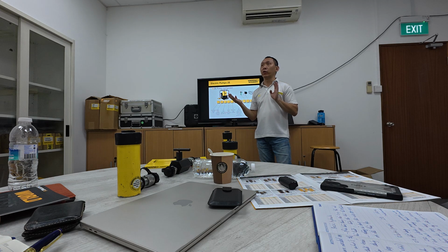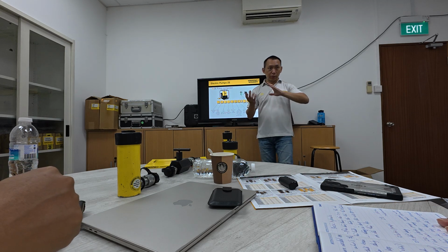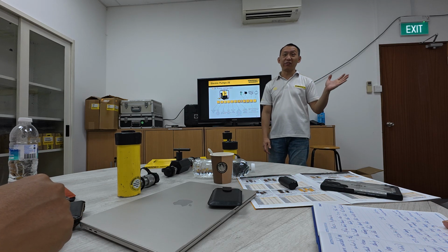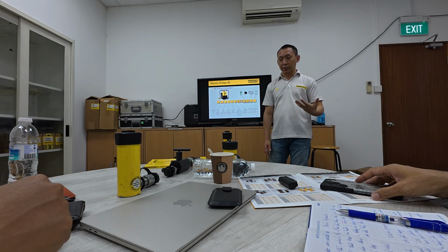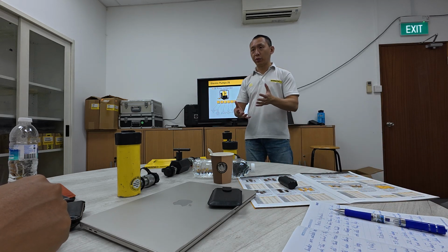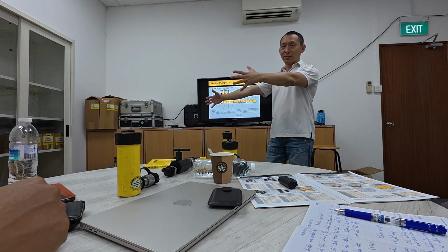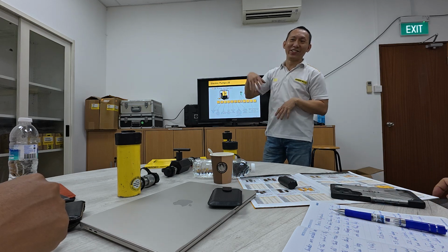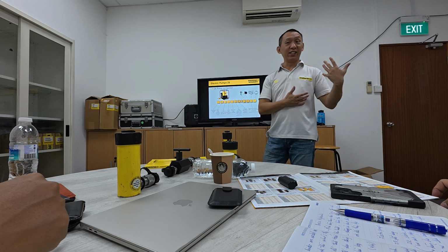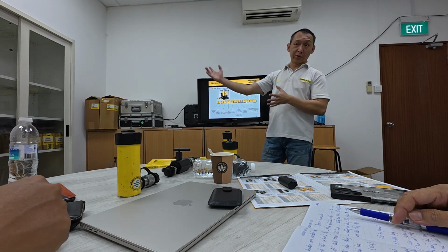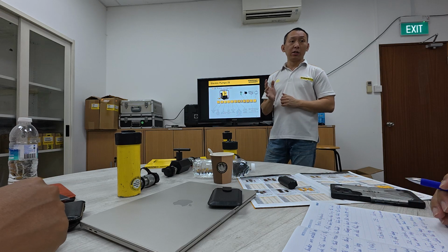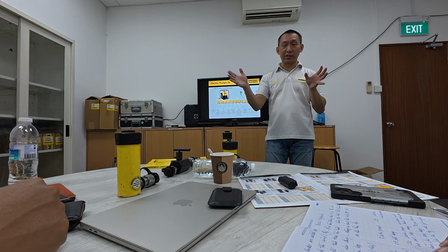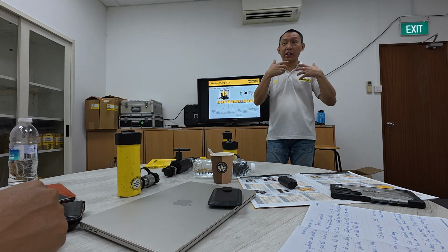If the customer wants a fast application, of course you use a higher flow, maybe ZE5 or ZE6. For example, if the customer is using a 1,000 ton cylinder and you use the ZE2, they sit there for half an hour. It's very slow. So you want to use the ZE6, the fast flow. You size the flow according to the type of application.